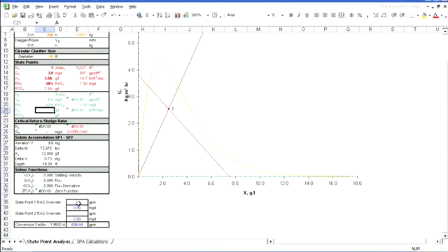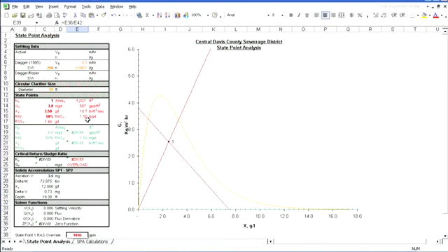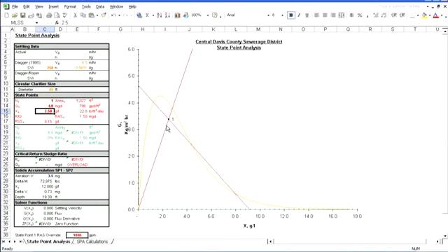Now we need to enter the value in gallons per minute in the override box down here, which conveniently gives us the conversions to mgd. And because we're really smart, we know that 1.5 mgd is 1045 gallons per minute. So we can enter that in here and it overrides up here above. And now we can change our flow to 4 mgd. And as you can see, our state point stays under the curve, but our underflow line doesn't. We know we are going to fail in thickening.